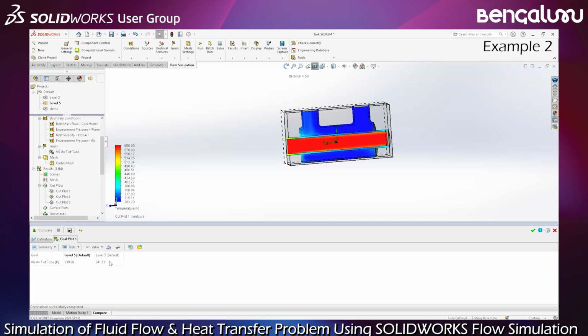If you have to deal with design change and so on, we may get the trends by dealing with a fast calculation, so using level 3, okay? And for validation, maybe you can spend more time dealing with the refinement of the mesh to get better accuracy, okay?